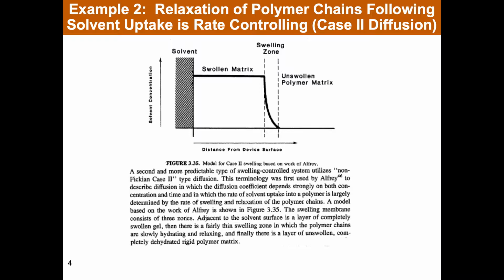So one of the underlying assumptions in the standard model of diffusion is that as a polymer absorbs a solvent, the polymer can swell to accommodate that penetrant in the same way that if you mix two solutions together, often very closely volume additivity is observed. However, that doesn't have to be the case. The rate at which the material or polymer can absorb solvent can be dictated by the rate at which the polymer chains can relax to allow that swelling to occur.